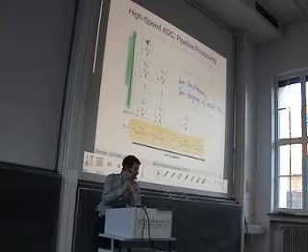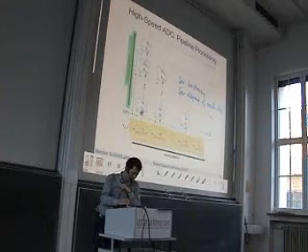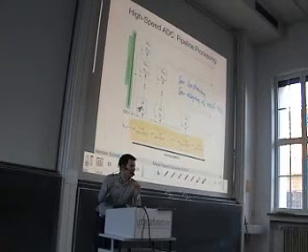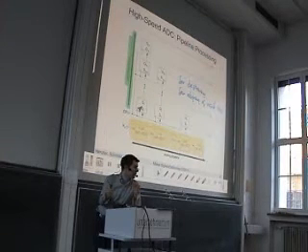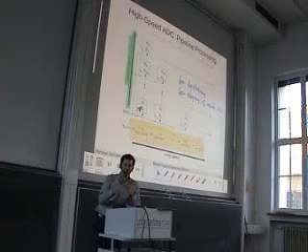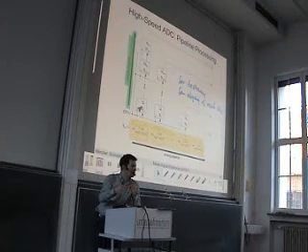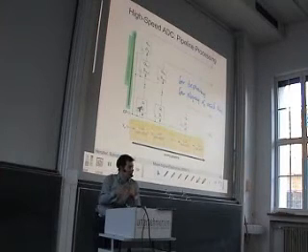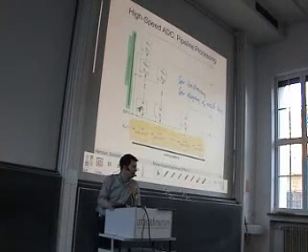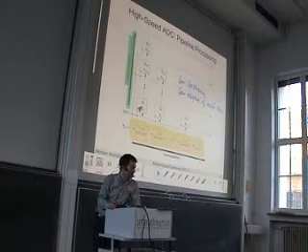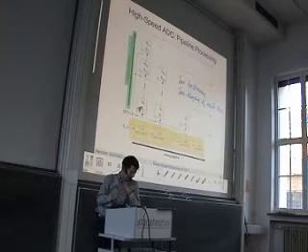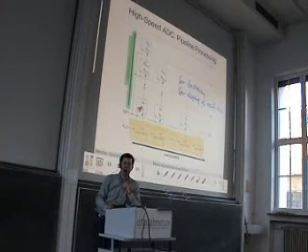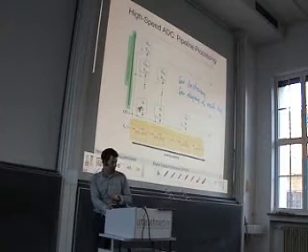However, it is totally wrong, because here in this pipeline we have a history of all previous n bits. If you would have a single flip-flop here with the divided clock, then we would have only 1 bit. So it would work, but only for every nth sample, not for all of them. So it is a failure to have only one flip-flop here with a subdivided clock. So we really need these flip-flops.